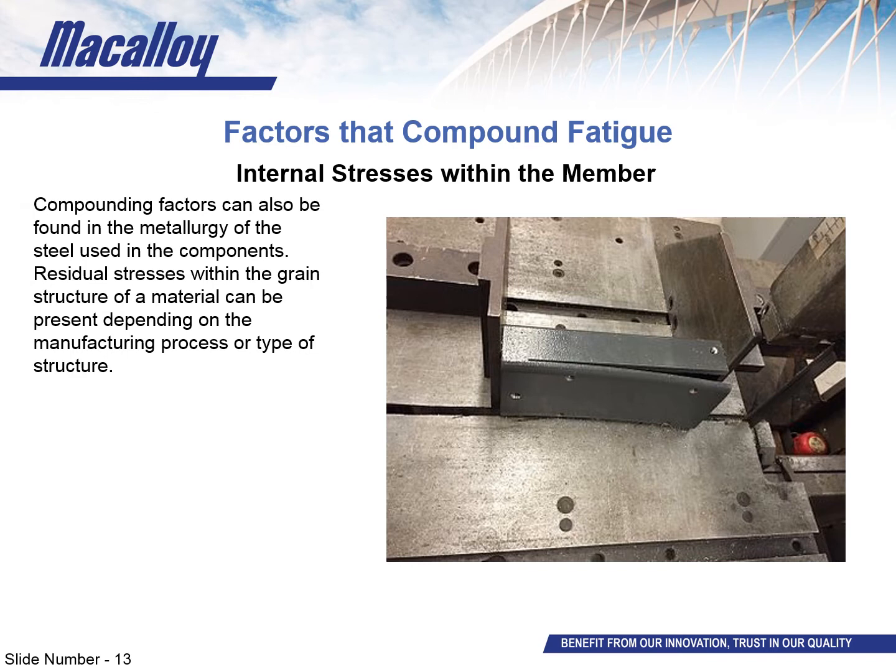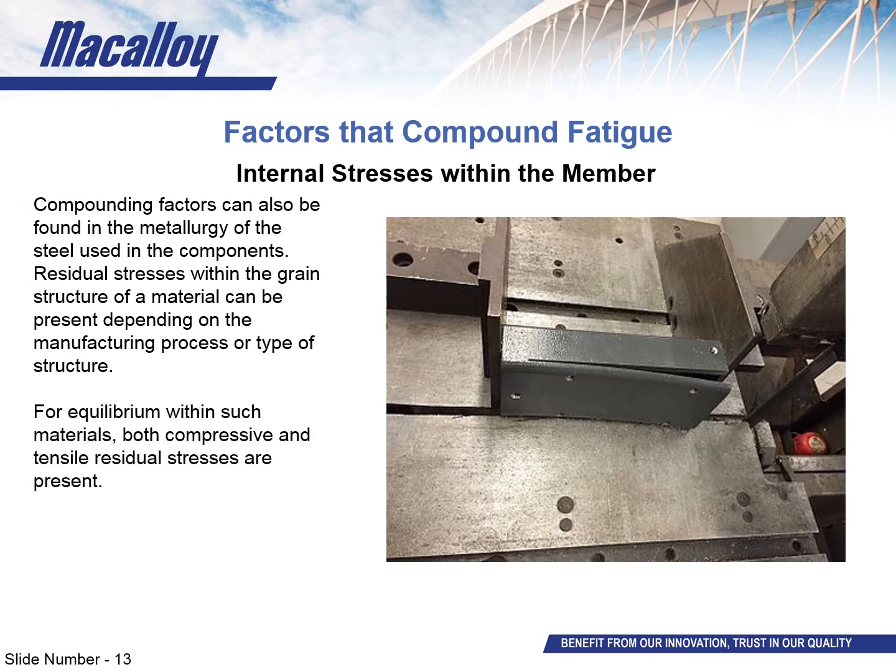Depending on which manufacturing route was taken, particularly when considering the cooling rates from the elevated temperatures in the manufacturing process, it's possible for residual stresses to form within the grains of the steel. As the raw material is sat on your shop floor, it's not moving there, so it's lying in static equilibrium. Now, for this to occur, the stresses within the material have to be balanced. For the stresses to be balanced, both compressive residual stresses and tensile residual stresses have to be present.